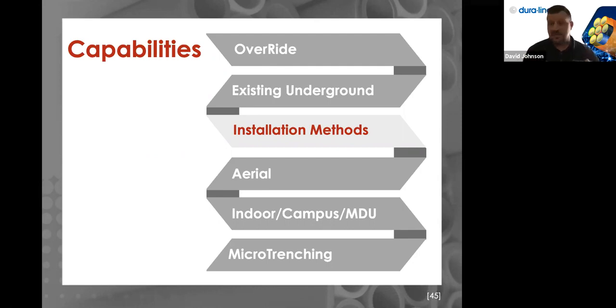And then what's the best way to do it is you have your jetting machine on the left side, and you're going to jet through 3 access points where you've got that microduct being placed straight through the handhole, if it's possible. With an override, it is. So you're going to couple that together, make it go straight across it, straight to the other side. You're going to blow through 3 access points. And then on that 3rd access point, far away from the jetting machine, you're going to jet in an additional 100 feet of slack loop.